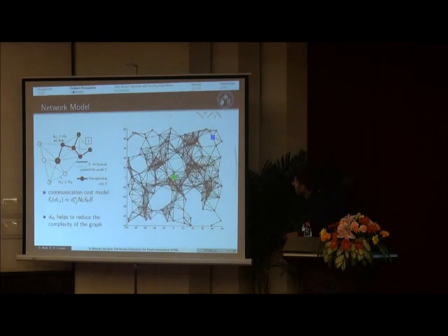Here is the network model. In our network model, we use a cost function, FC between sensors i and j, proportional to the distance between them, where these are the noise power levels, SNR, and fixed bit length. These are constants, and the cost depends completely on the distance between the sensors. The path loss exponent is experimentally supported, so I use values between 2 and 4. And DTS is a threshold distance. That means if the distance between two sensors is greater than DTS, we are not going to communicate with that sensor, neighbor or parent. By that, we reduce the complexity of the algorithm. But we have to ensure that each sensor can be reached by the other sensors through the network, so that is controlled by DTS.